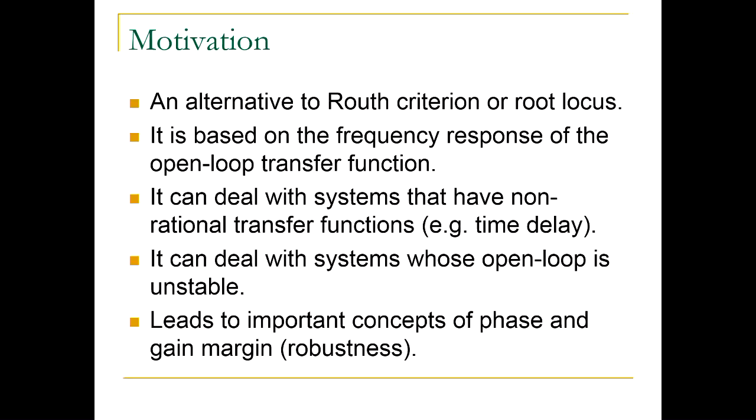So Nyquist criterion can be applied to systems with time delay. We can plot the frequency response. By the way, Routh-Hurwitz does not apply in that case, right? But this criterion does. So in other words, this is a more general stability criterion than just Routh-Hurwitz criterion.